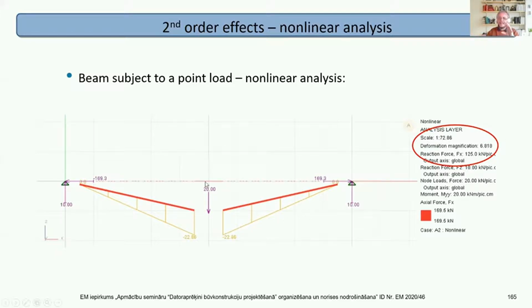This says the deflection is actually considerably smaller than it appears, and that's getting better. We also note that there's quite a lot of axial load in this now. It was acting as a beam, now it's acting as a tie in many respects, with a bending moment. The bending moment is pretty much the same, and there's also consequently a large horizontal reaction to balance out the axial loads. So this is the difference between a non-linear and a linear analysis in this situation.